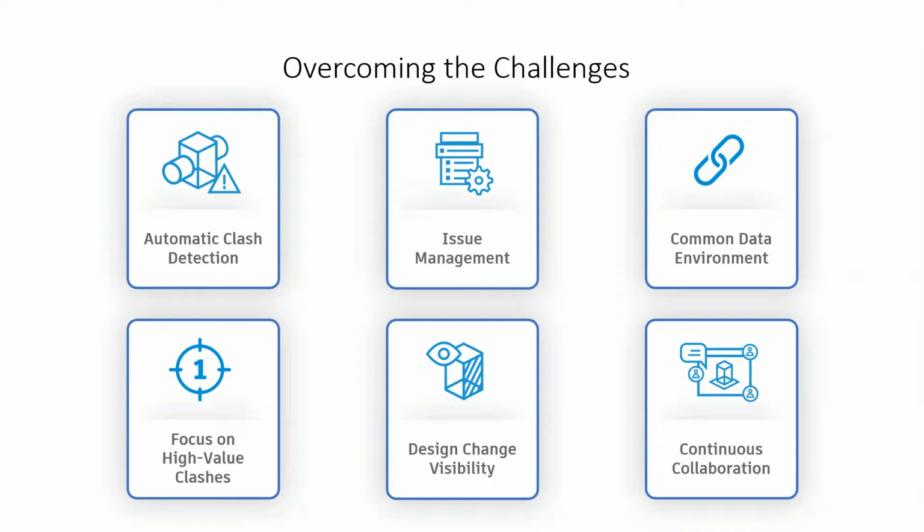With something like BIM Collaborate, you'll start to see that as soon as the models are shared, there are workflows that can be set so that they are automatically clashing, and you can keep an eye on those clashes. And even though you're not in Revit, you're not authoring, you're part of the reviewing team, obviously, in the cloud. You can start to view those models and review those clashes within the tool. So you can create issues. You can then assign those issues out and then track those issues, right? So you're not having to wait for that information to come through from the actual authoring parties. Okay, so that's just a little touch on that. We will talk about that a little bit further in a little while.